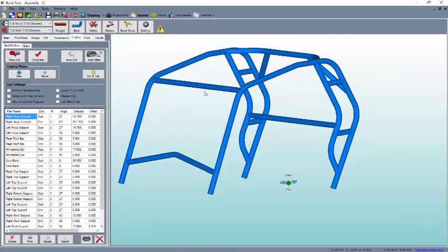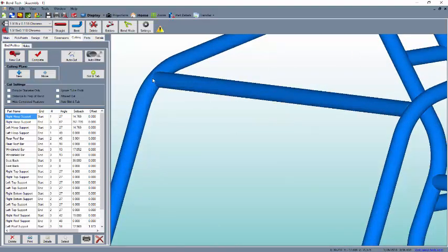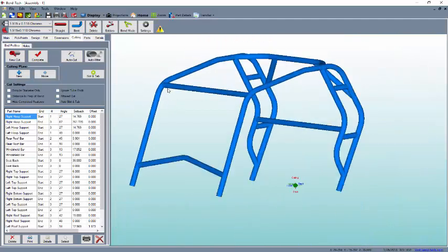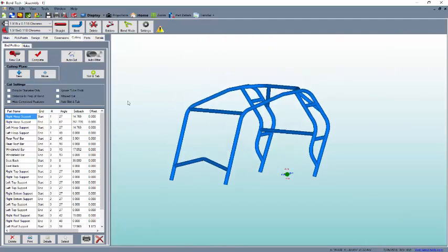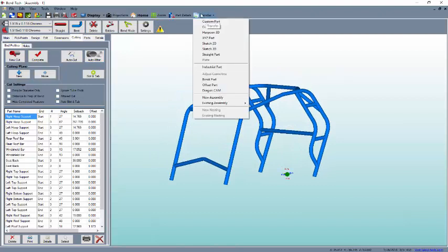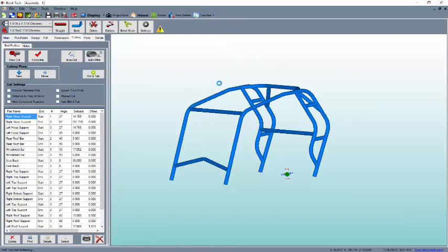They don't auto regen. So if I change the die on a part and say it's a larger radius, well, this bend right here is going to drop. So that cutting pattern is going to be changed. I'll just leave it with the dies I have applied. We'll transfer the entire thing to Dragon Cam. Show you what that looks like.